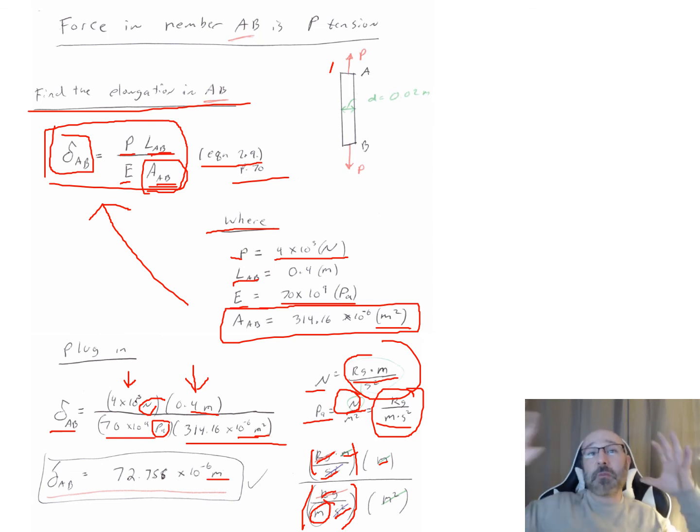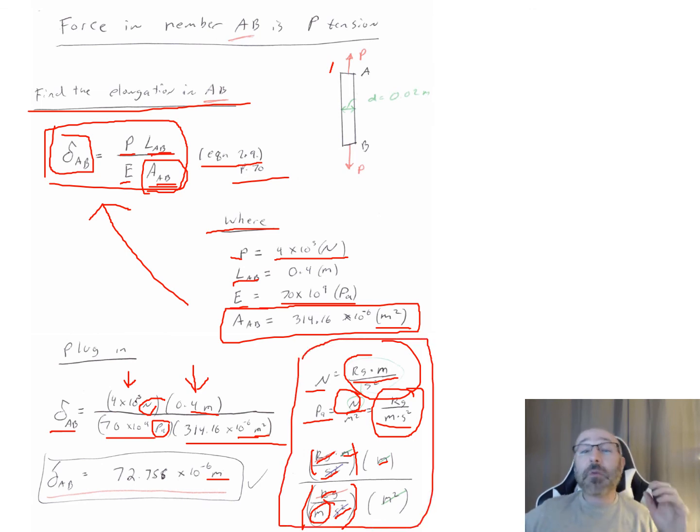I know this is a little bit extra step along the way to do these all out with all this unit analysis over here on the side, but it helps a lot, and it's a great way to double check your work. Did I plug in correctly? Did I use the right units for my modulus of elasticity, for my loads? Did I plug this in right with the right units for area there? And if it doesn't check out, it's a good alert for you, a red flag that something was wrong. I didn't do my unit analysis right. I didn't have my conversions right. I plugged in a wrong value. Do that out with all these problems. It's going to save you a lot of time and really a great way to double check your work.